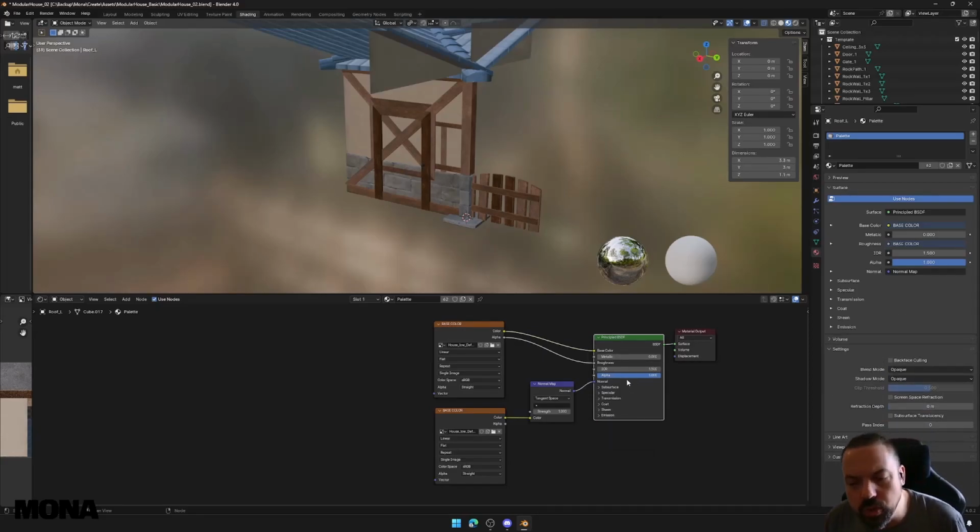So the ones you usually use with game assets, and that's the key thing, game assets, will be diffuse, roughness or smoothness / specular if you wanted to. Normal is definitely a big one. Emission as well. You do have other things like ambient occlusion, so the darkness in shadows and stuff. Not sure if you can use that in here, but maybe there's another node instead of principled BSDF. I haven't really looked into that. That said, that's getting more complicated than you probably need. So stick with the main ones, especially if you're new to this.